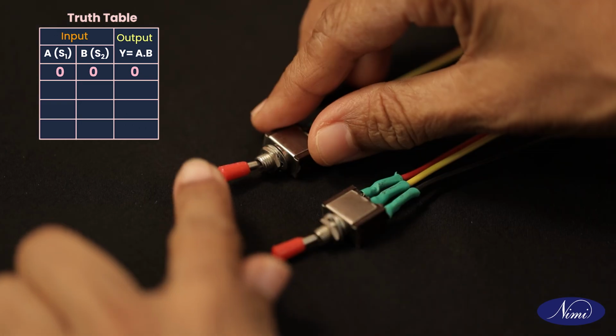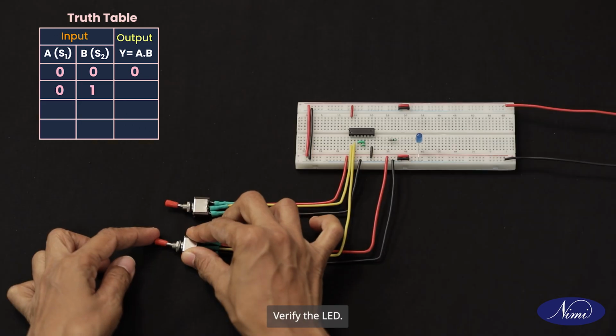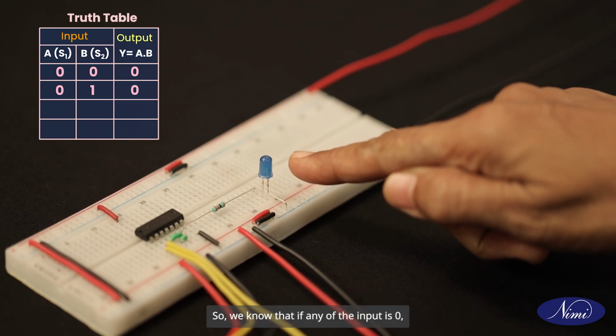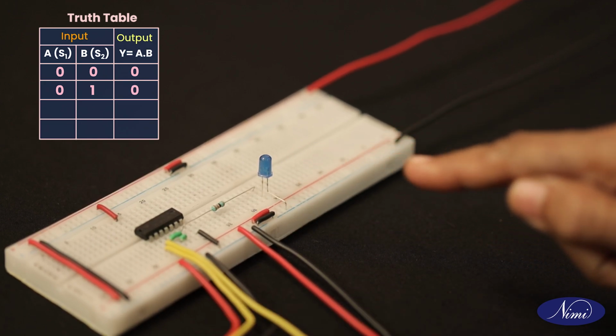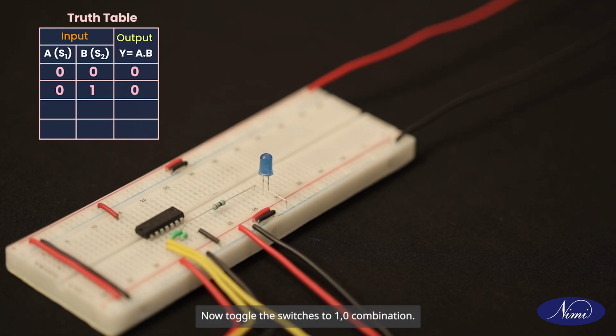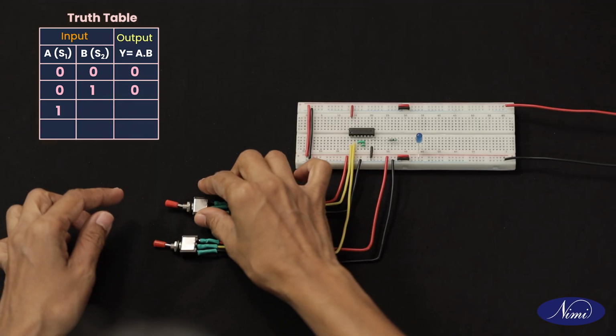Now, toggle the switches to 0-1 combination. Verify the LED. It is still not glowing. So, we know that if any of the input is 0, AND gate produces the output 0. Now, toggle the switches to 1-0 combination.